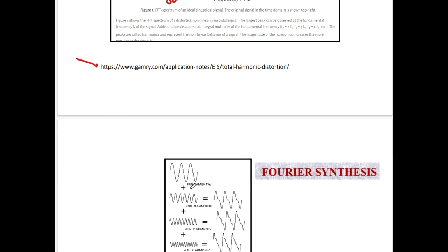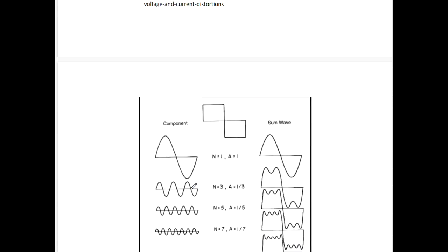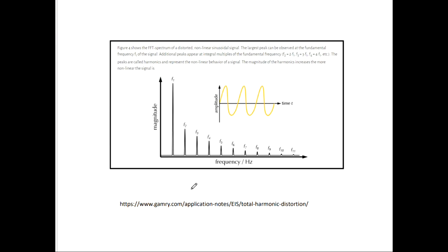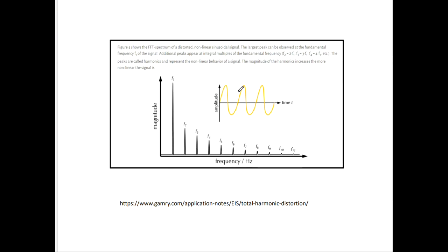Let me stop right there. Let me just come down here for a second, and I'll go back. Let's say we look at an imperfect sine wave, a sine wave that's been distorted. Well, distortion is the addition of harmonics by our amplifier or by our nonlinear system. It's going to add harmonics and distort that wave.